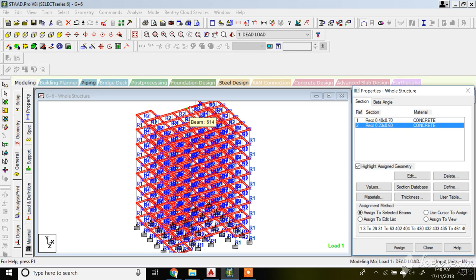Any extra modeling, any modification, you can do in your own geometry, your design. You can increase the number of stories, you can do whatever you want with the geometry. But there is one more shortcut, I'll discuss it later. If the loading is the same throughout, like every typical floor has the same loading, then the translational repeat we used can also be used for the loading repeat. But we are not using it.